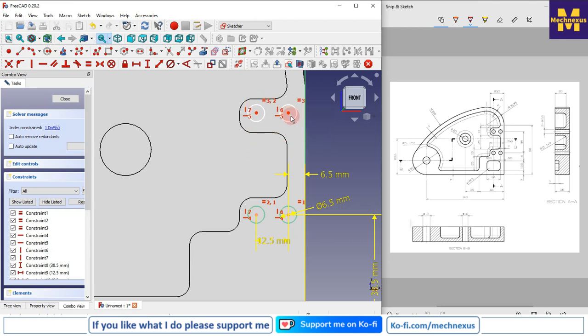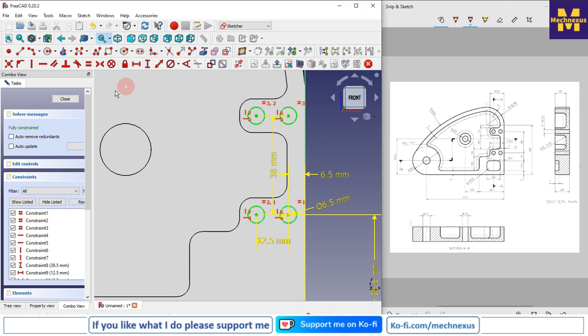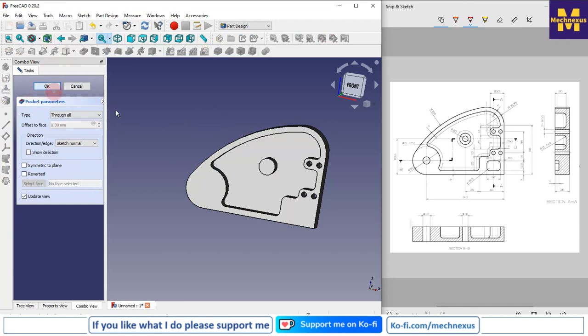Now this hole to this hole position is 38. Now I will close my sketch, and this hole is a through hole, so I will go with a cut, and I will say through hole. I will say OK.